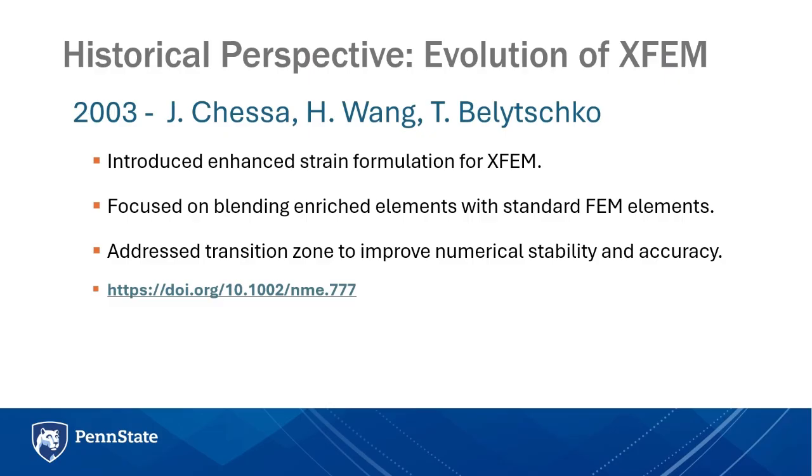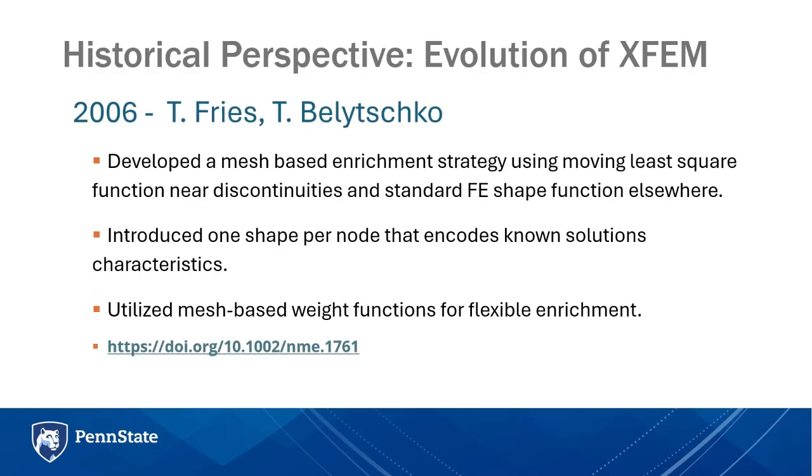Another major work of 2006 developed a mesh-based enrichment strategy using moving least square functions near discontinuities and standard finite element shape functions elsewhere, introduced one shape function per node that encodes non-smooth solution characteristics, and utilized mesh-based weight functions for flexible enrichment.